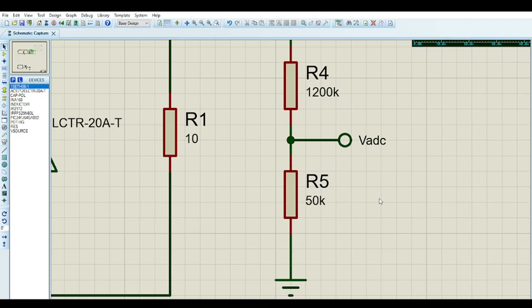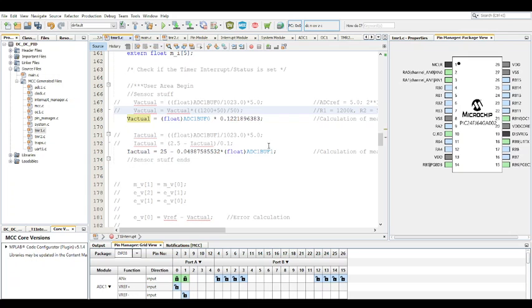I know it's a tiny bit of power, but for these particular resistors, I'm guessing you might be using quarter watt resistors. They get hot because literally they can't take more than quarter watts, and you don't want your sensors getting hot, because once they get hot, the resistance changes, and then this reading you're having here is basically useless.